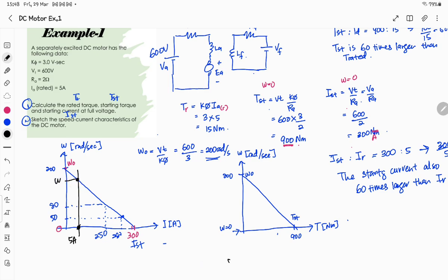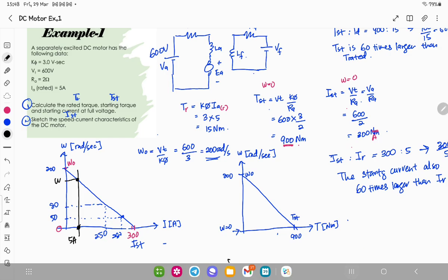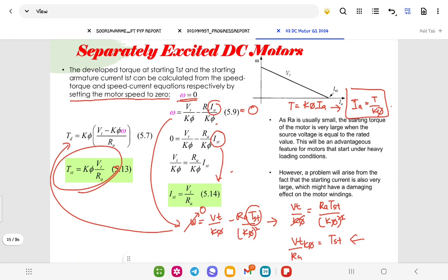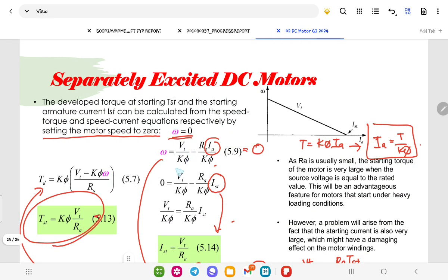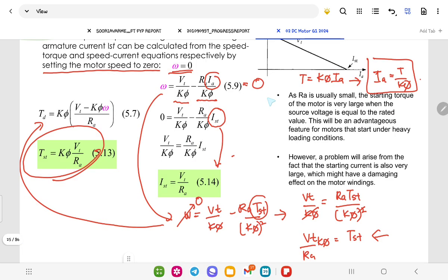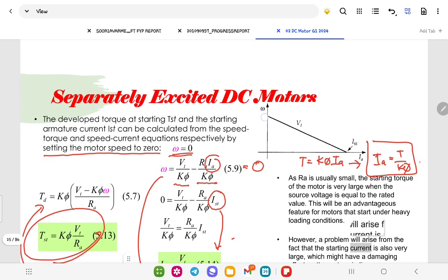Okay, motor speed. Remember, the motor speed equation consists of two terms, which you can see in this one: the no load speed and the speed drop. From this equation, this is the no load speed, and the speed drop is the slope of the line of the graph.